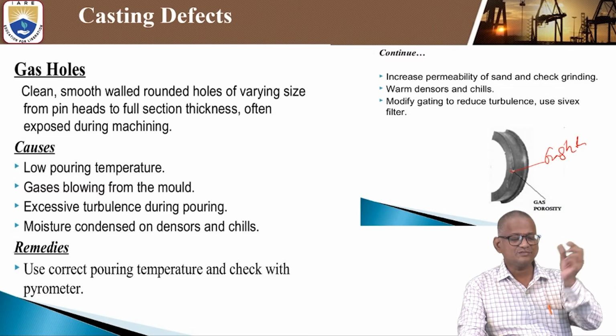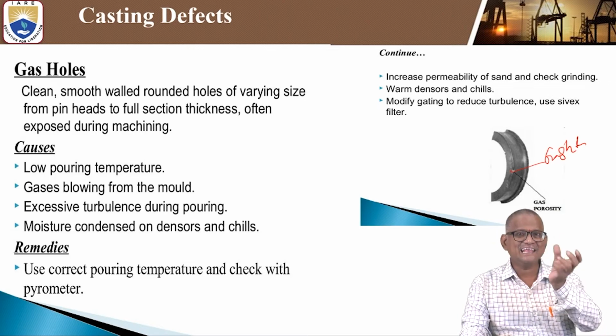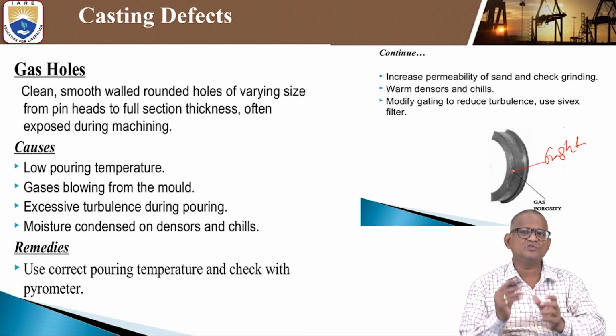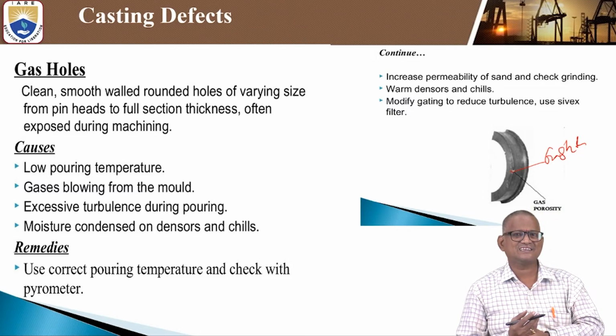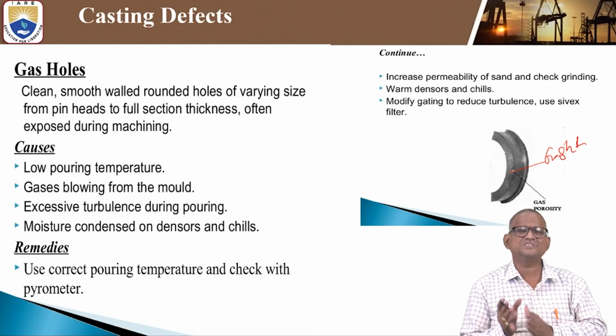The term gas holes can be defined as clean, smooth-walled, rounded holes varying in size from pin heads to the full section of the thickness, often exposed during the machining process.